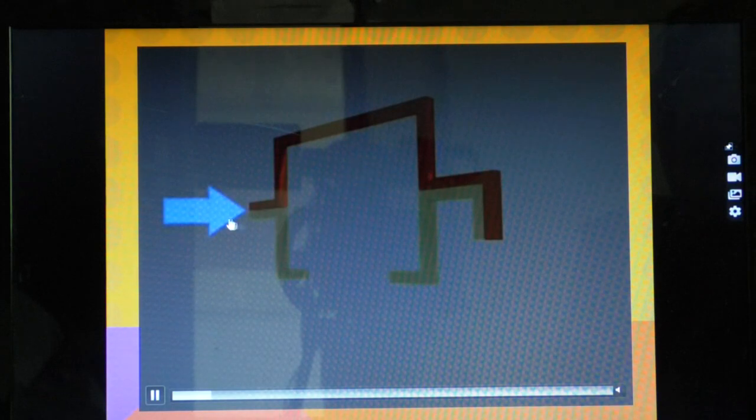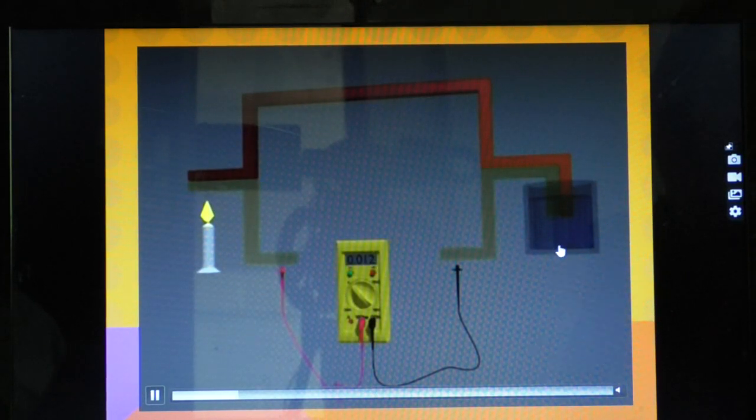Let us come to the laws of thermocouple. For this purpose, let us take two metallic strips of two different metals forming two junctions. We have joined them here at this point, the junction, and at this point, the other junction. This junction is exposed to a high temperature, that is a flame, and here is a cold junction, that is cold water, and the two terminals are connected with the terminals of the ammeter, and the ammeter is giving you some current.